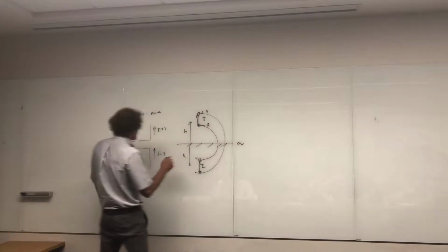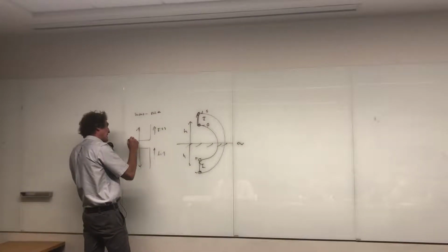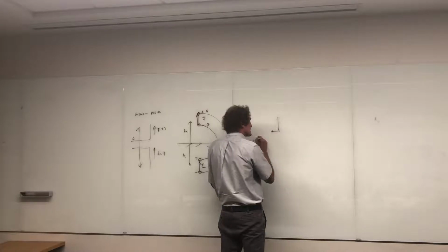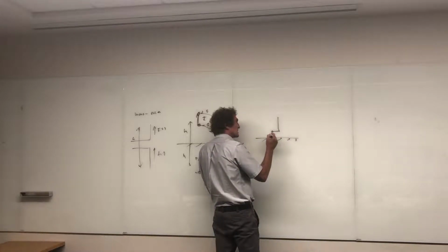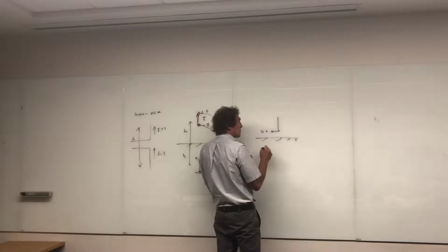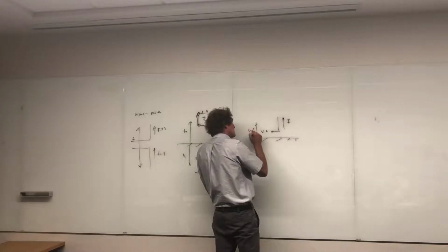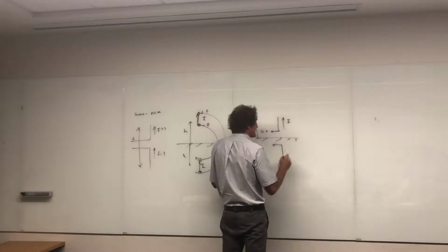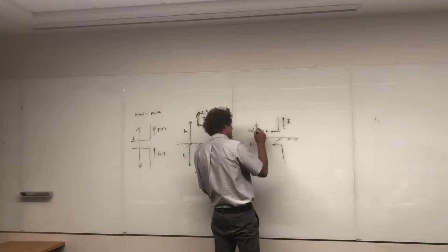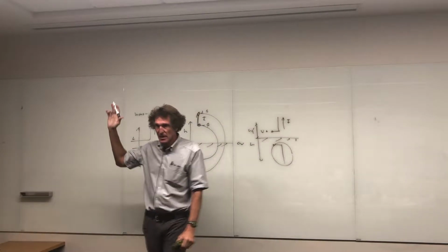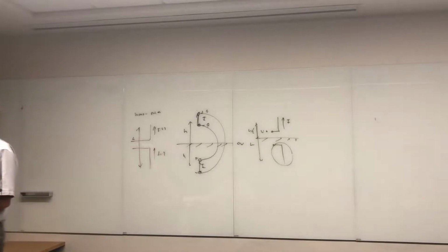So if we have this, which was typically a dipole of length L, I can say that for a monopole, and this is the way a monopole looks, it's grounded there, with a small gap, and they'll have a plus voltage there, and the other part will be just grounded. They're going to have a current I here. A monopole has a length L over 2. They usually do this. That means the total length of this is L, right? But now this is just an image current. Do you all see this, class? In other words, effectively the monopole for currents in the vertical direction just extends the monopole to double its length and makes it look like a dipole.